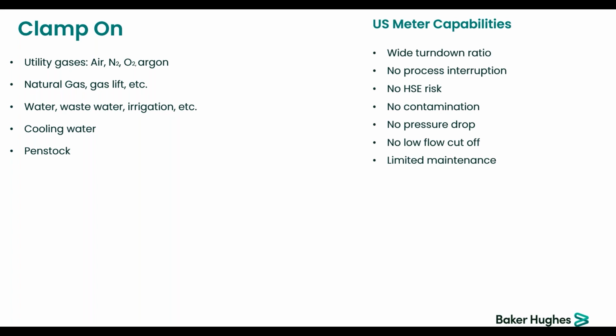But the reasons for adoption of the clamp-on are kind of the same, but also because there's no need to tap on the line or to cut anything, there's no HSE risk and no contamination risk associated with it, compared to the other advantages that we covered earlier.